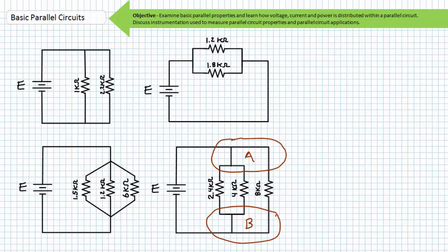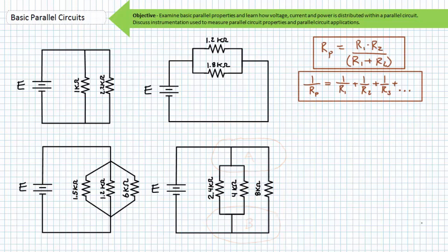We'll return to the utility of such alternate depictions of parallel circuits when we discuss Kirchhoff's current law and the current divider rule in later lectures. Recall from the fixed resistors lecture that the total resistance seen by a source for a parallel combination is always less than the smallest resistor composing said parallel relationship.